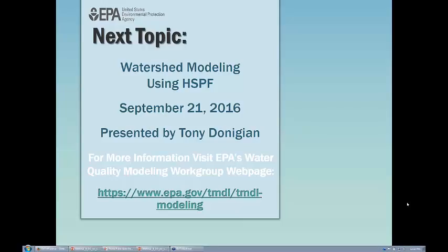It's a bad idea to go into any modeling project with a preconceived idea of what is going to be good enough, because good enough is a function of how much information you have about the system, but also how much information you have to model the system, both hydrologically, hydrodynamically, and water quality, as well as how much knowledge you, the person doing it, have. I've seen water quality studies where the model was being asked to resolve a question that you couldn't resolve with a DO probe. So that's probably a bad idea.